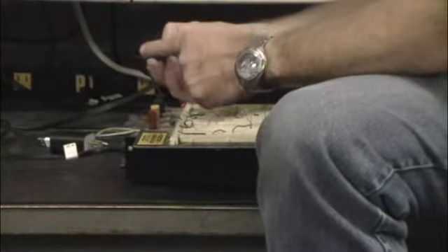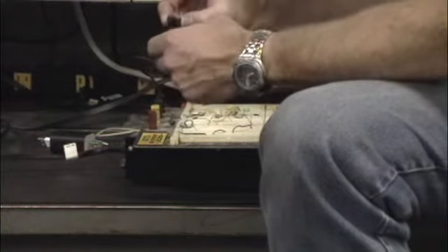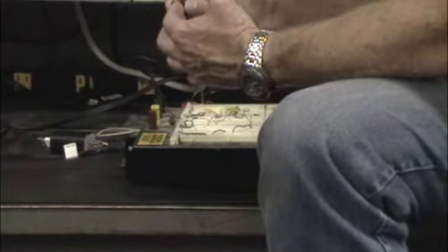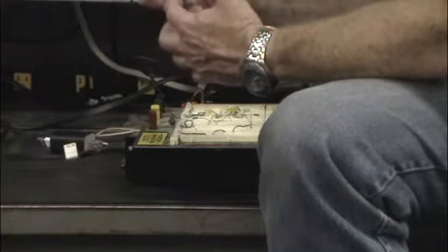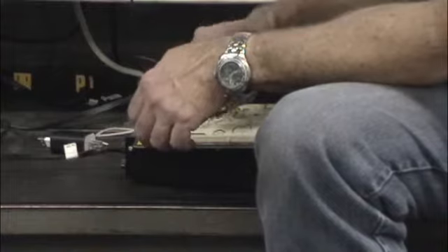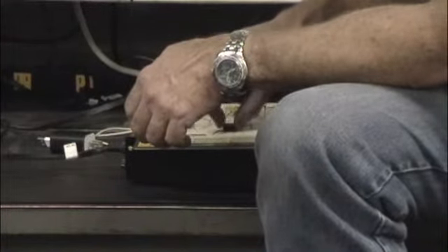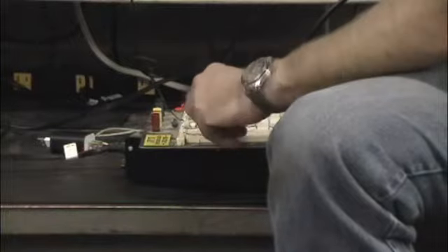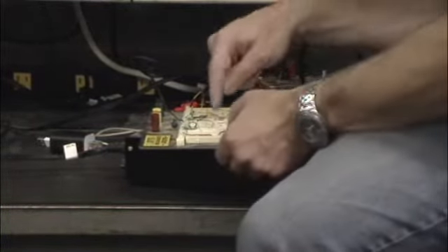It has 4 pins on the underside. And when I press the button, it connects these 2 pins to these 2 pins. So this is basically a wire that runs across the inside of here. And you want to line the pins up with the 2 things. So now I can drop a wire in where the pin was, or on the same line as the pin, and this thing here breaks it so I can have two halves of the circuit.